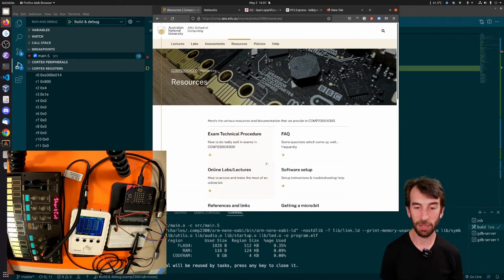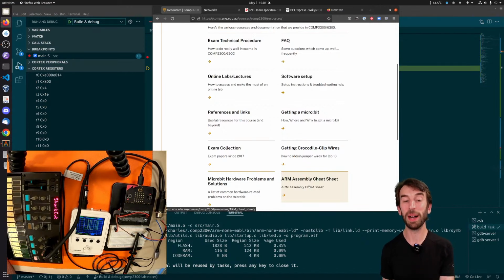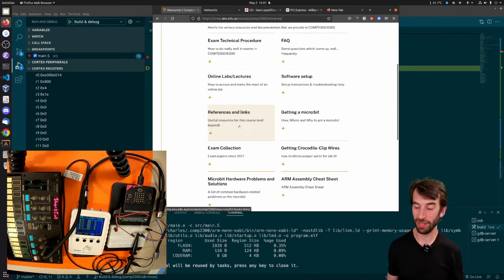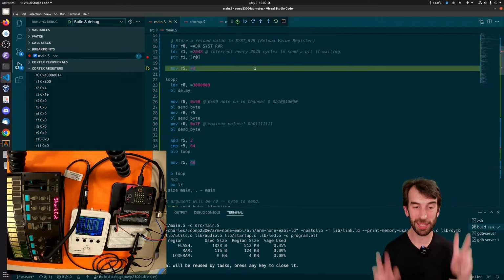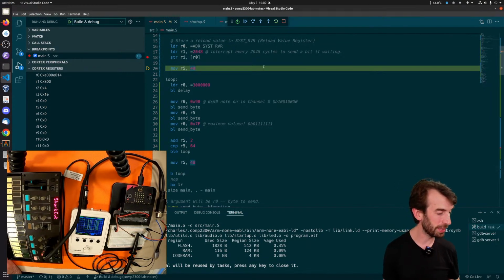There's a bit of hardware called the UART, which is specifically hardware designed to send bytes over a serial connection. So you don't need to run your own timer to send a UART connection. You can just use the UART peripheral, which has a timer. I'll show you how to set that up on Thursday, I think. So this is in some way the hard way, but it's the way that lets us learn how to do it using a timer.